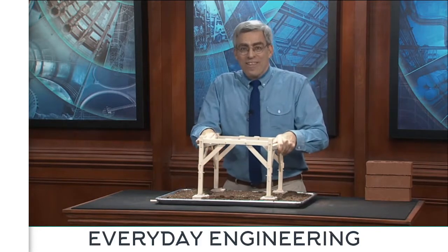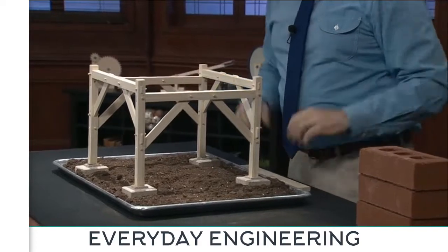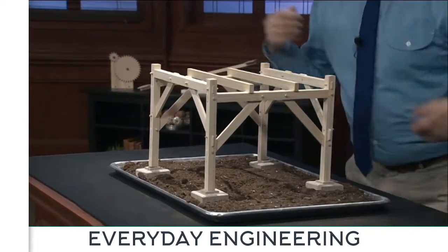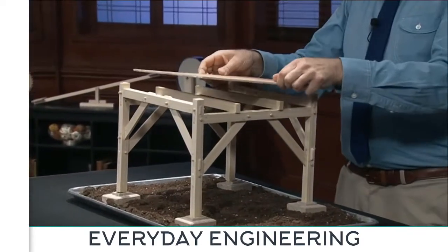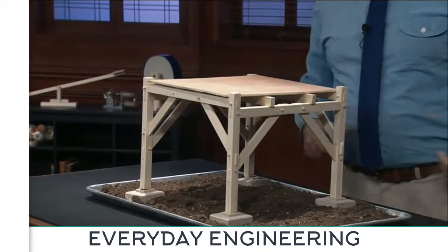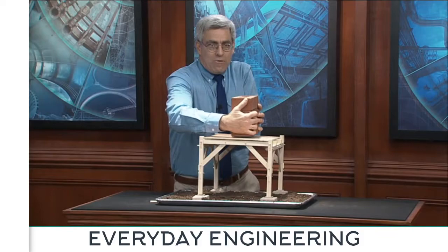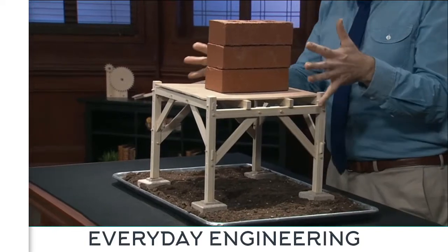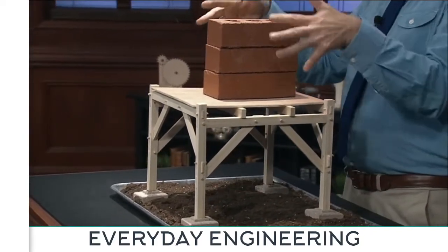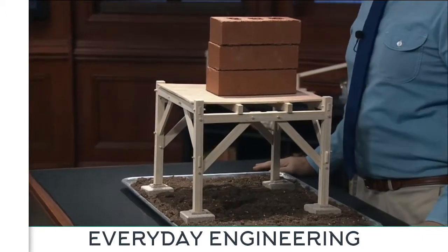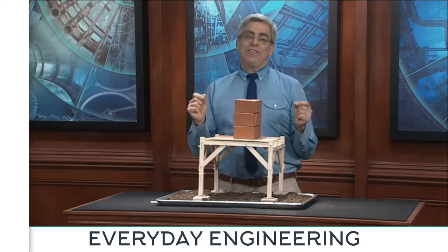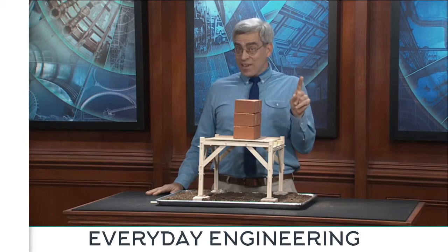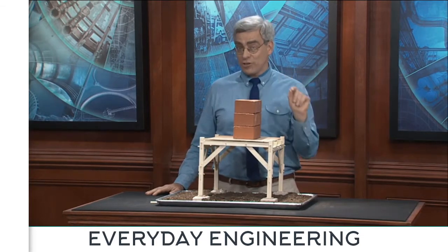Wow. Notice now that the structure is significantly more rigid. I can now add a floor system to the assembled three-dimensional frame. I can put an actual set of floor planking on top of that floor system. We can now apply substantial gravity load and lateral loads simultaneously, and none of the previous instability that we saw in this frame is present, despite the fact that we have substantial amount of loading on the structure. This demonstration dramatically illustrates the inherent rigidity of the triangle as a structural form. We'll see this concept again when we talk about trusses next lecture.